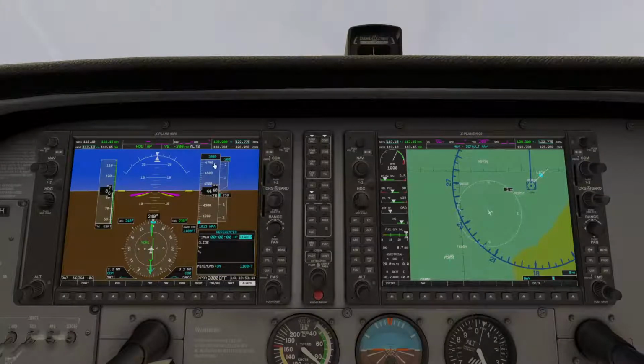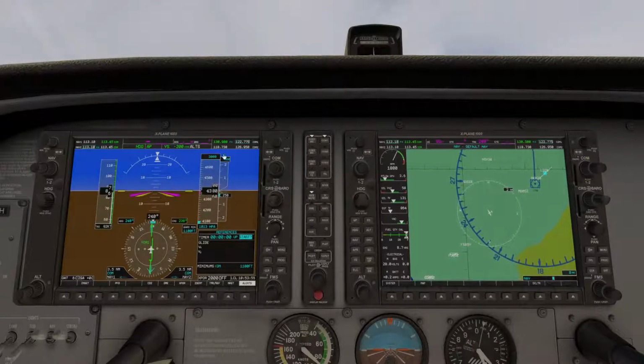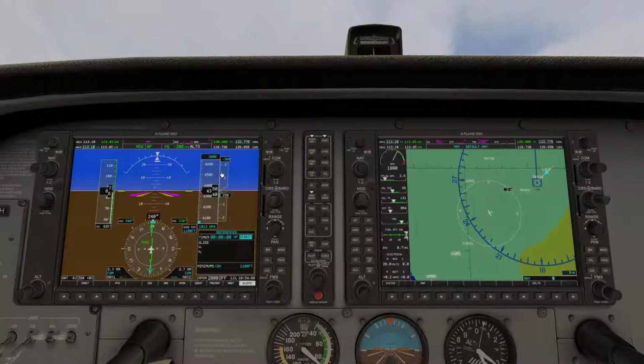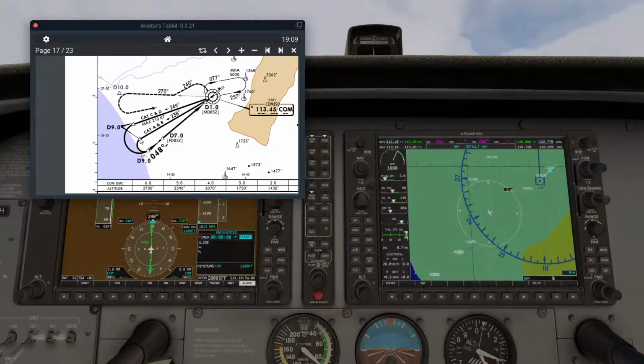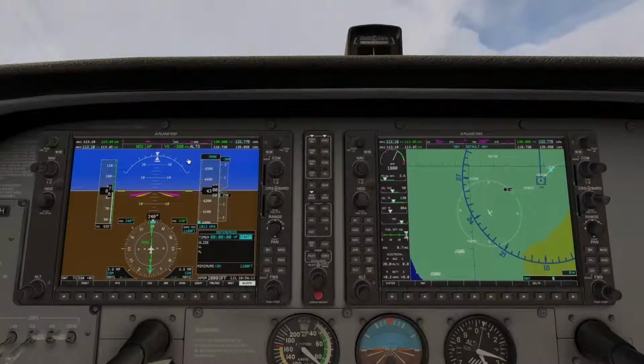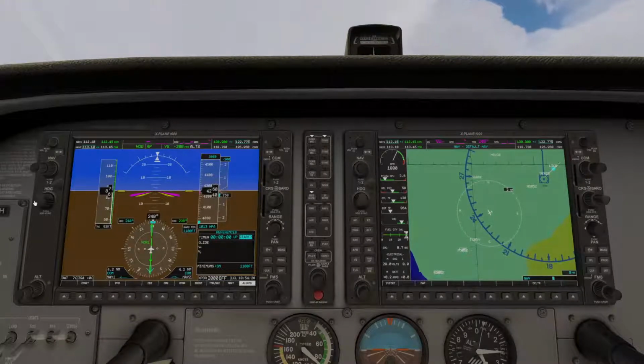Remain to reach the 3,000, but as you can see there is a turn after reaching 9 mile out. As I think, minus 300 feet per minute is okay for the vertical speed, and we will be at 3,000 feet when completing this turn. Watching the CDI, it is center and this heading is good right now. Maybe, as I think, 239 is better.